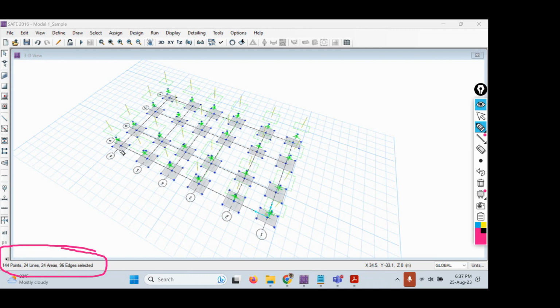But we don't need it in this way. We want to assign the loads only for columns. Why? Because column load will be different. Whatever load is coming from the column, all that load will get transferred to the footings. So whenever you are assigning the loads, even in pictorial representation, we always represent the loads that are coming from the column like this only. We never represent the loads like this on the footing slab, right?